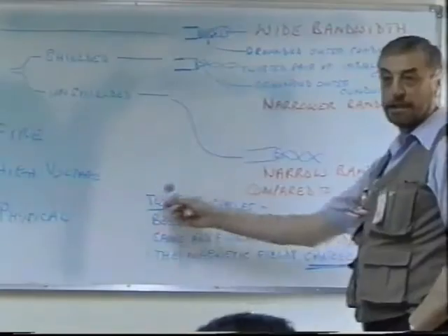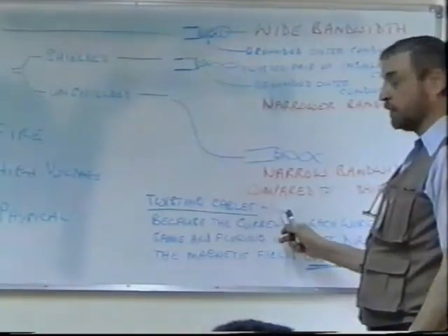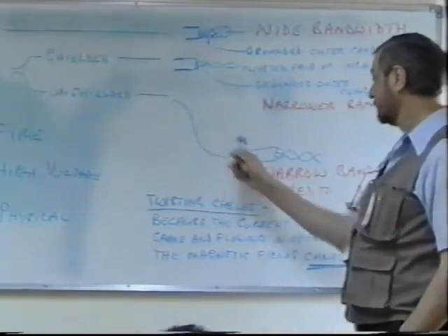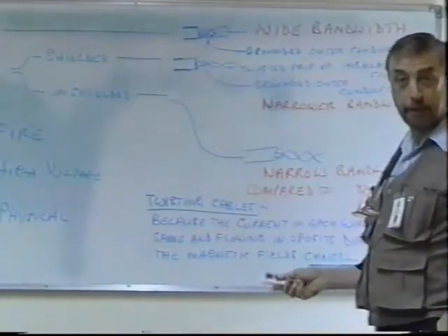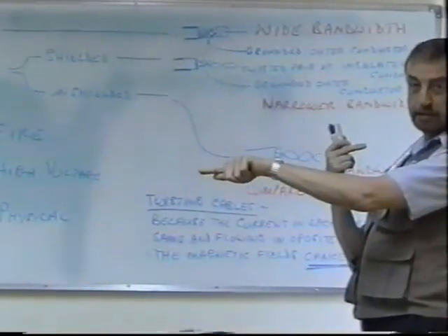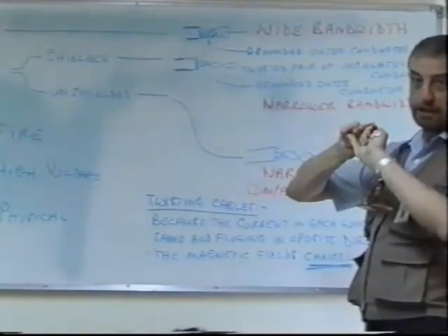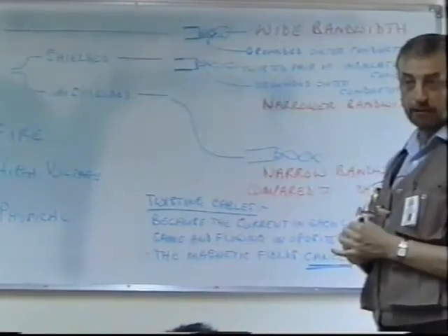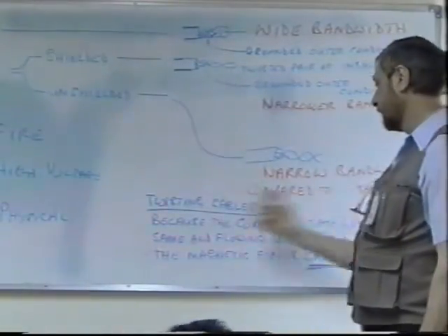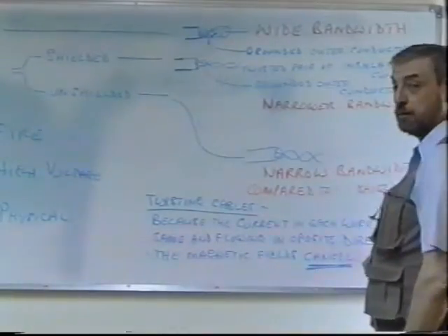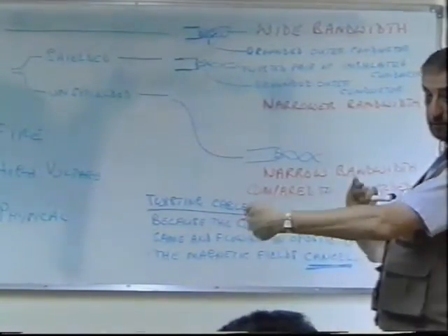This little bottom piece here explains why we twist the cables together. Because the current in each wire is the same, but flowing in opposite directions to form the circuit. Usually the wires you twist together form a complete circuit. So the current flow in each direction is the same, hence the magnetic field produced will cancel.